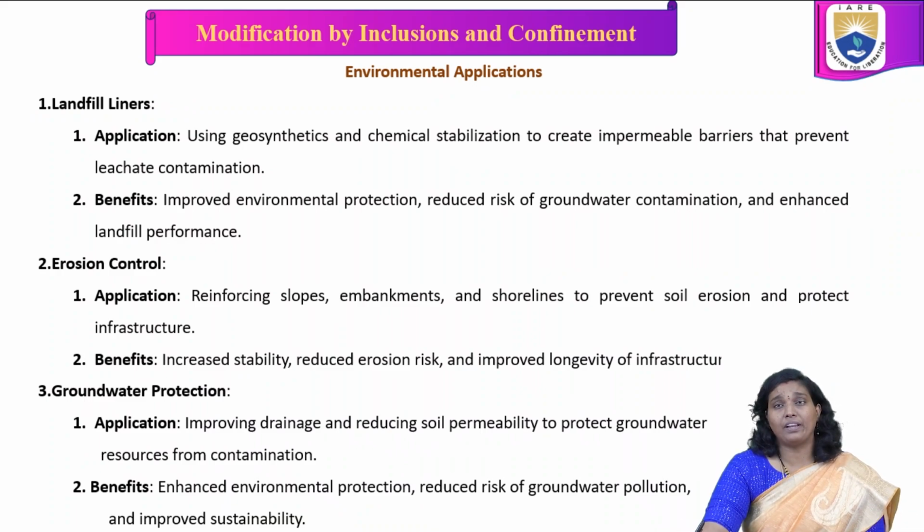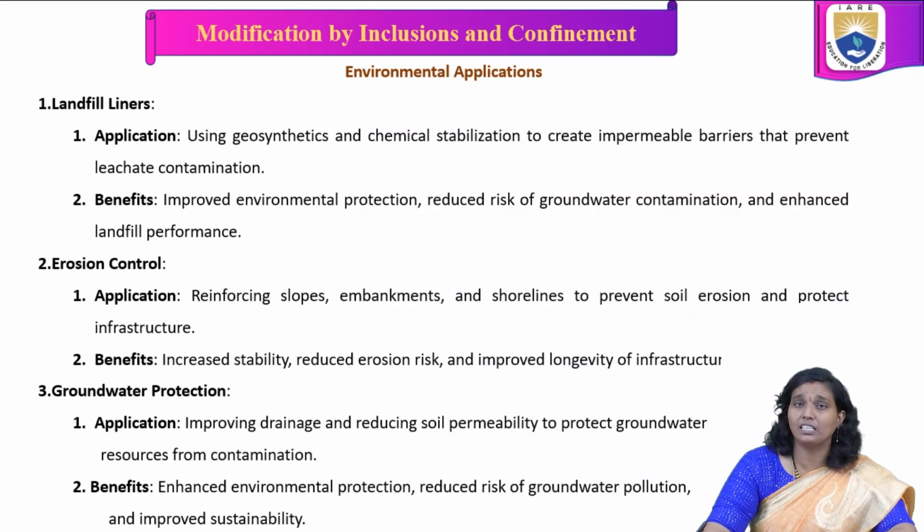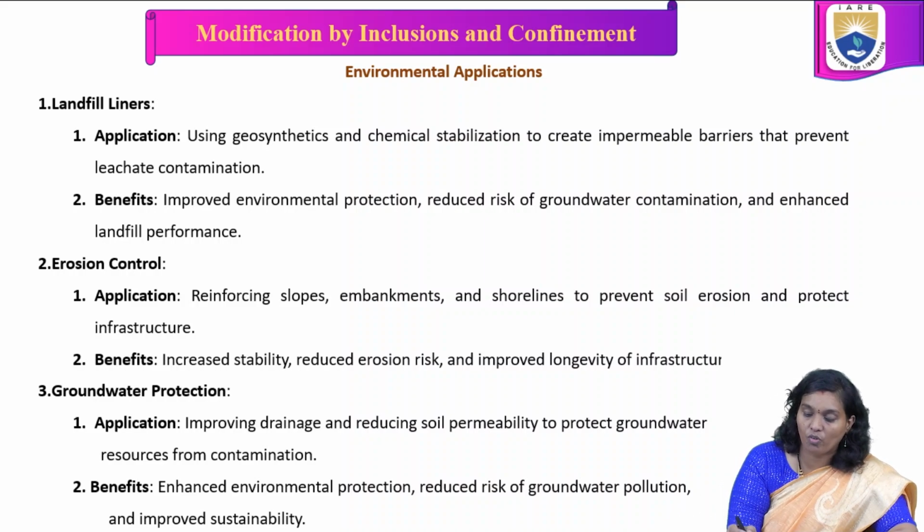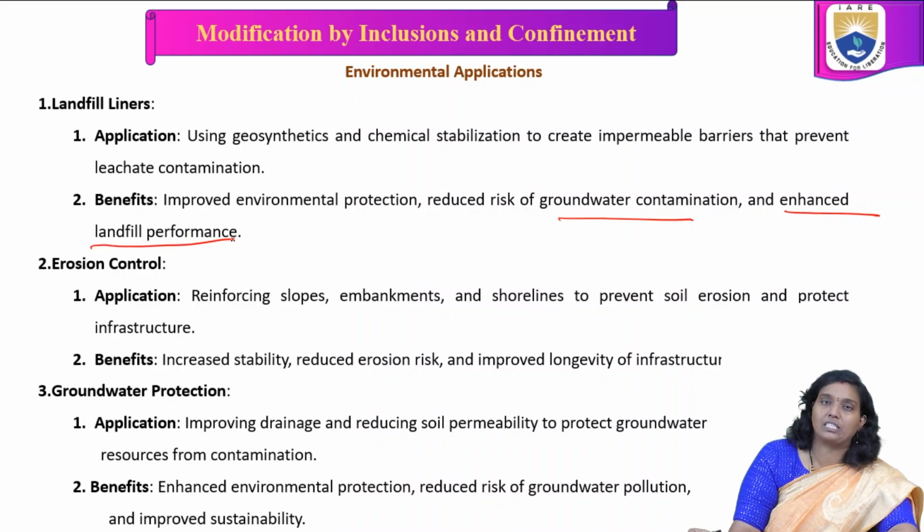In environmental applications: landfill liners, erosion control, groundwater protection. In landfill liners, we apply confinement using geosynthetics and chemical stabilization to create impermeable barriers that prevent contamination. The benefits are improved environmental protection, reduced risk of groundwater contamination and enhanced landfill performance.